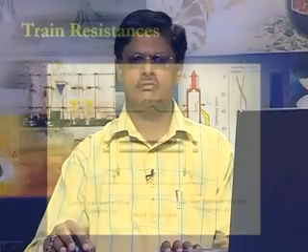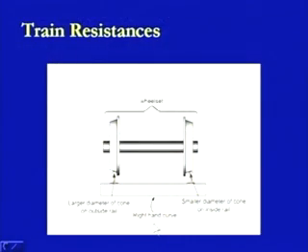Here we are looking at this diagram, where we are trying to check the right hand curve. Now when there is a right hand curve like this, there will be a centrifugal force which will be acting in the lateral direction towards the left hand side. When there is a centrifugal force acting in this direction, this axle will move in this direction laterally, and because the wheels have been coned, there will be a larger diameter at this side and a smaller diameter on this side.